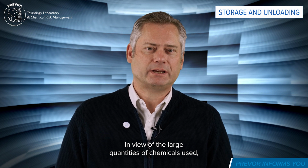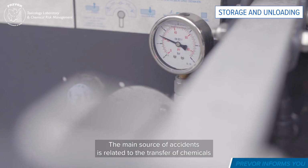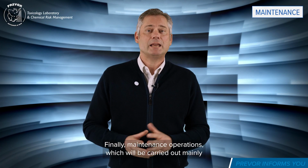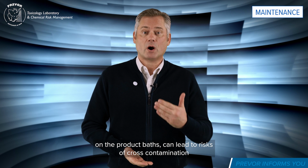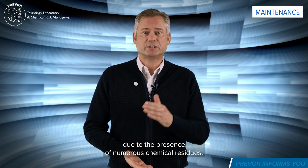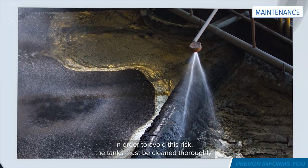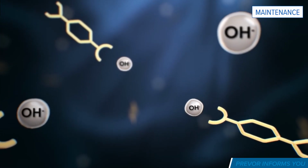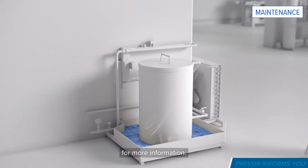In view of the large quantities of chemicals used, the storage and unloading areas are also risk areas. The main source of accidents is related to the transfer of chemicals from one container or tank to another. Finally, maintenance operations, which will be carried out mainly on the product baths, can lead to risks of cross-contamination due to the presence of numerous chemical residues. In order to avoid this risk, the tanks must be cleaned thoroughly, in particular with a neutralizing chemical decontaminant, such as Safurex. We invite you to watch our video on equipment decontamination for more information.